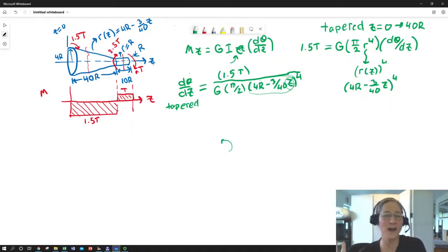And if you think about it, you can think about moment of inertia as resisting strain, just like it resists acceleration. It's kind of a one-to-one with dynamics. So you've got your moment at the top. The bigger your Izz is, basically the smaller your angle of twist. That's related to strain. If you were in dynamics, we would say it's a smaller alpha. So basically we're changing our moment of inertia smaller as we move in the positive z direction. The taper could have been going the other way, in which case it would decrease as we go forward.